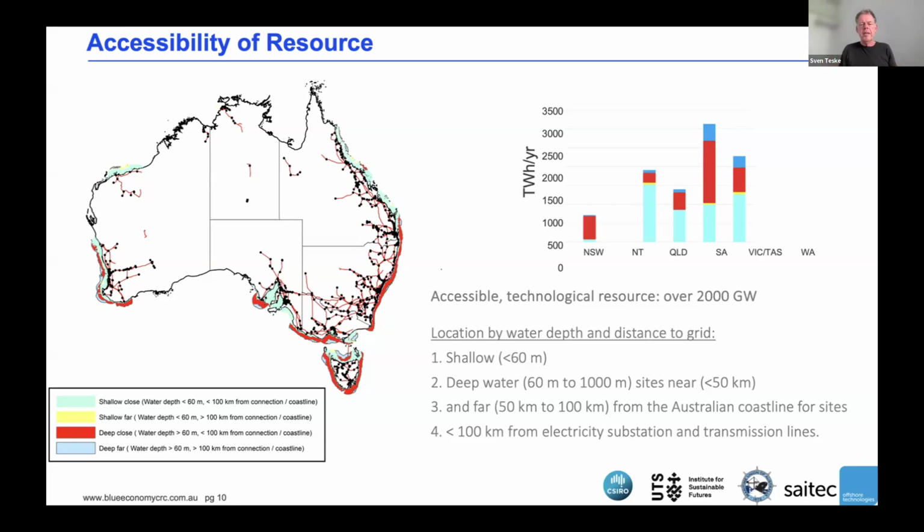But it also shouldn't be far away from the land. It should be less than 50 kilometers. The reason for that is quite obvious. You have staff, and you need to move equipment back and forth from the shore to offshore locations. 50 kilometers is about 30 nautical miles roughly, and that means if you have a speedboat with maybe 15 knots maximum speed, you need 2 hours to get there. So basically, you don't want to have it too far away from the coast.